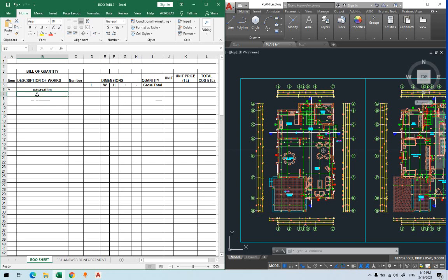We'll take that 15 centimeter out of the land. But in order to do that, we need the site plan, not just the area of the building, because that top stripping, 15 centimeter or 10 centimeter, they will take from the topsoil. That will be the site plan.